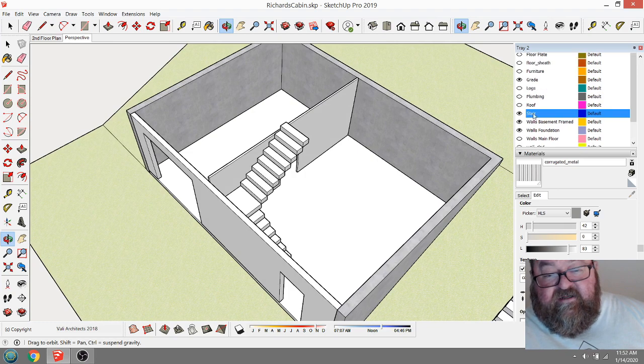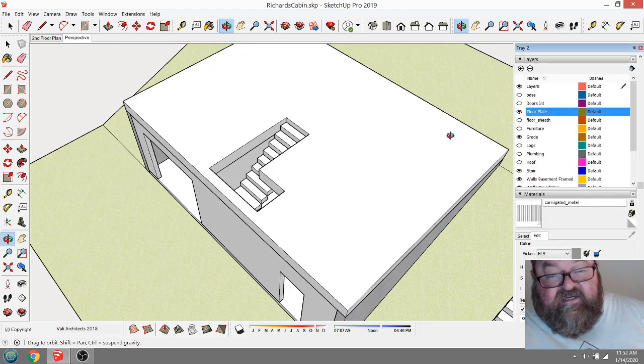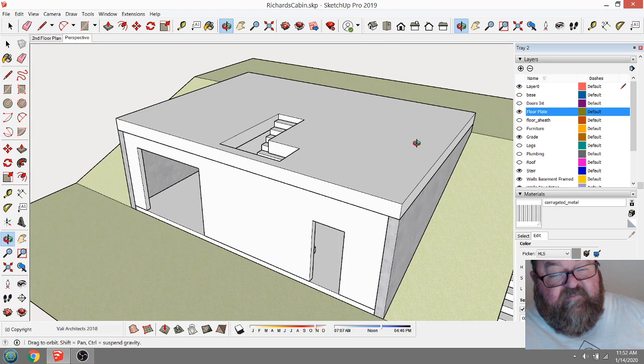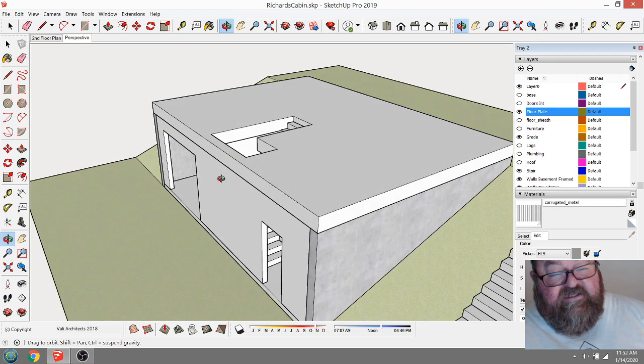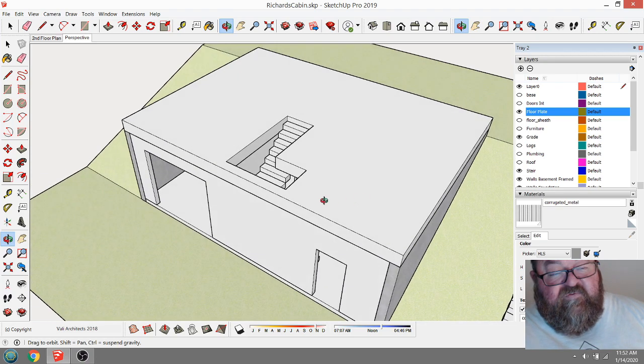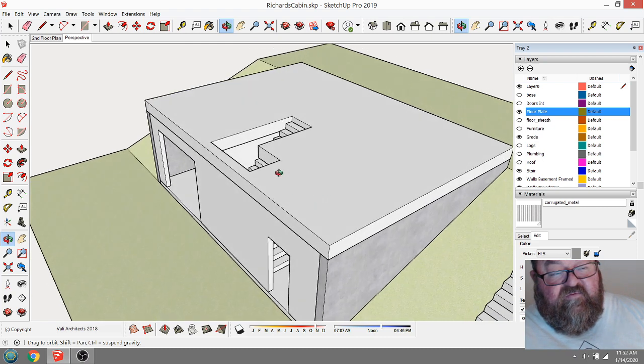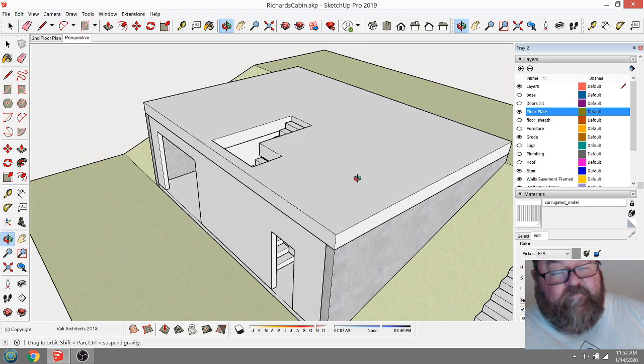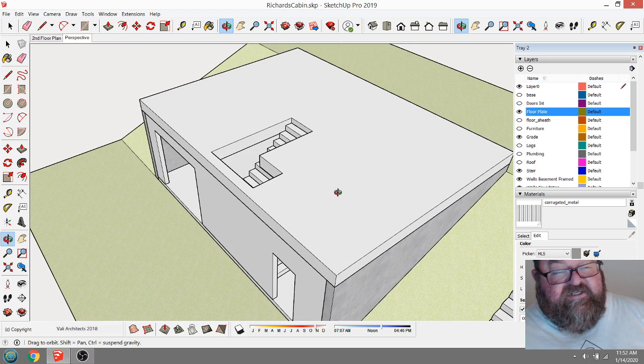So then that brings us to our floor plate, and I'm envisioning this floor system being out of some floor trusses. What I call, well, there's a company that has this product called trim joist that look like floor trusses, but they're easy to cut. You can cut the ends of them to cut the lengths on them.